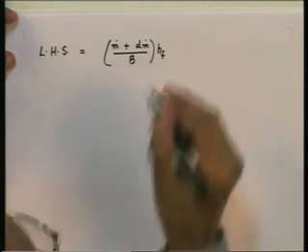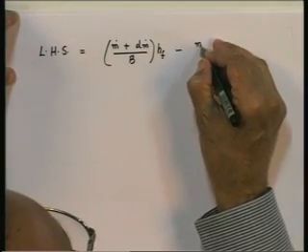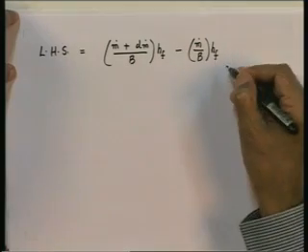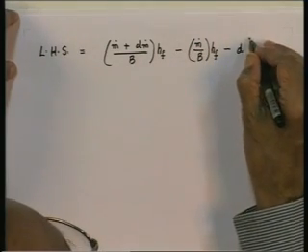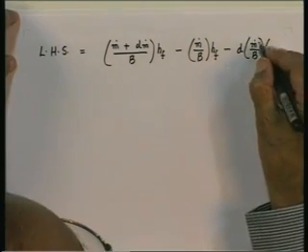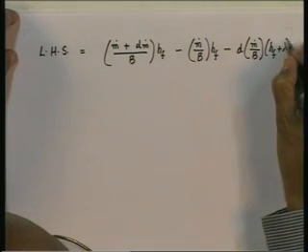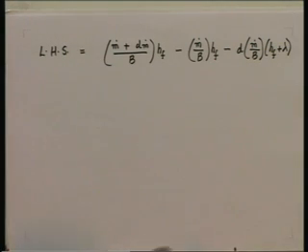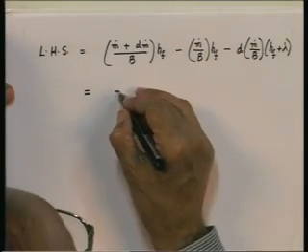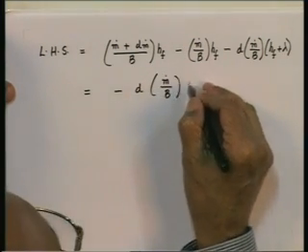This is the enthalpy leaving the control volume, minus the enthalpy entering at the cross section Z, that is m dot by B into H f, minus the enthalpy entering where the vapor condenses and becomes liquid, multiplied by the rate at which it enters, and this is the enthalpy per unit mass, because this is saturated vapor being converted into saturated liquid. So, multiply by H f plus lambda. So, the left hand side is nothing but, on simplification, minus d of m dot by B lambda.